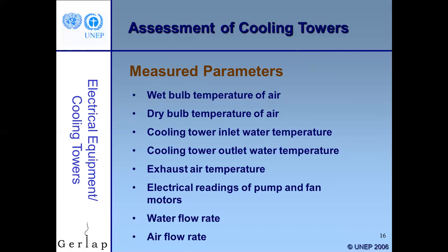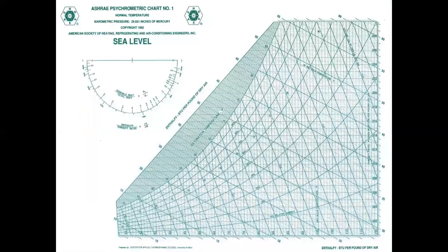That's of interest: exhaust air temperature, electrical readings on the pump and the fan motors, the water flow rate and the airflow rate. Those are all important parameters to know.